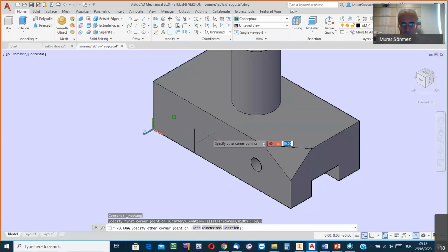It is important. You see in the simulation I have no width and height boxes. By clicking on the comma key after writing the first number, I sent a message to the software. I said that the first number is not the width, but the abscissa value for the second corner point relative to the first.